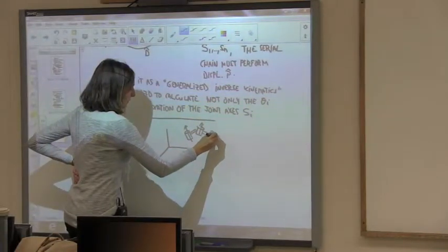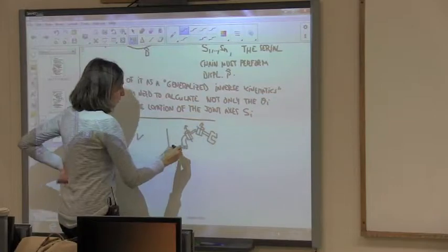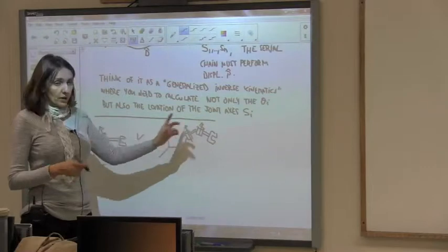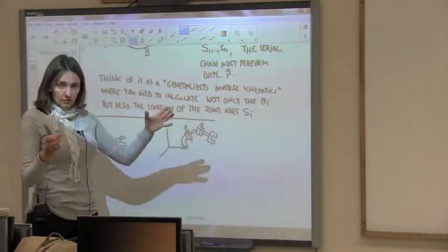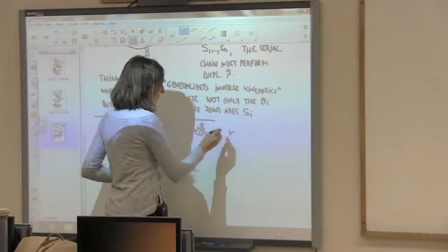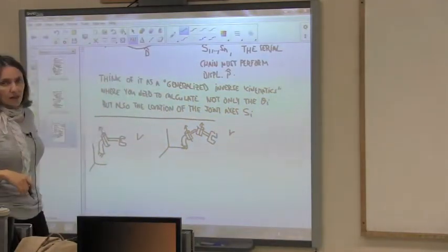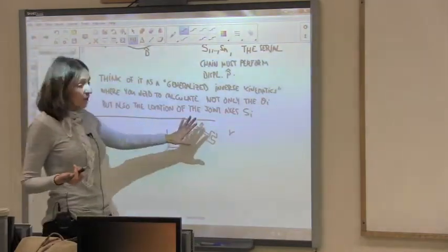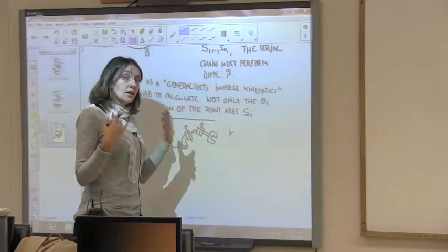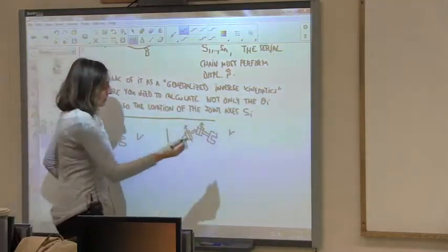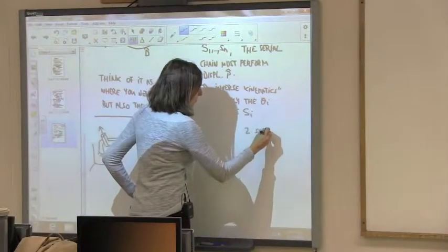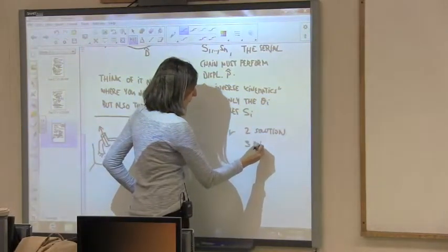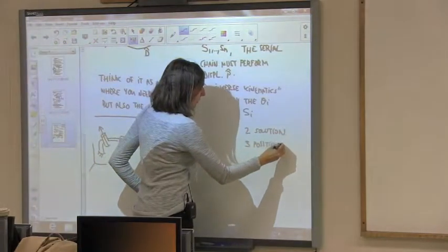And now, what we want to know is, you are given your task, and you need to locate this first joint, then look at the angle and the distance between these two joints. This one is easy. This one is done. I'll show you later what you get. In this one, actually, these are very nonlinear systems, so you get two different solutions, two different robots that can reach up to a certain number of positions. Two solutions. And the maximum number of positions you can define is 3 positions. We will do that counting next.